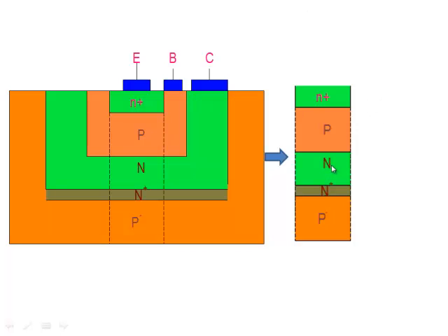And in this transistor, we'll see the role of P minus is, you seldom make one transistor on a wafer. You make several transistors. So the role of P minus is to isolate one transistor from the next. We'll see that later on. And N plus is simply there to provide a good contact to the collector here. So many times P minus we ignore, N plus also we ignore, and we draw like this here.